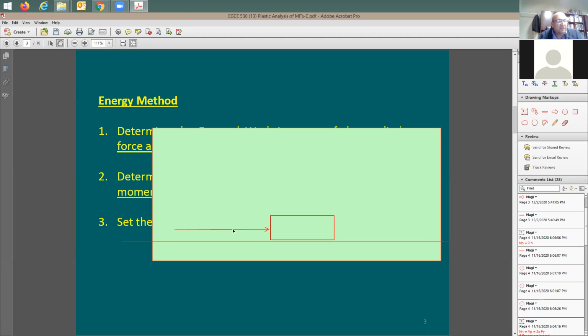So when it comes to force, I'm going to say the force is pushing it in this way. So I'm going to say force times displacement. In some cases, I'm not going to have a force, I'm going to have a rotational force. What's the rotational force for us? I'm going to say rotational force is going to be a moment. So actually the moment you can consider to be a rotational force, if you'd like to call it this way. In this case, the moment is not really causing direct or linear displacement. It's going to be causing a rotation. So the energy, which means the work, is going to be equal to this rotational force, which is a moment, multiplied by this amount of rotation.